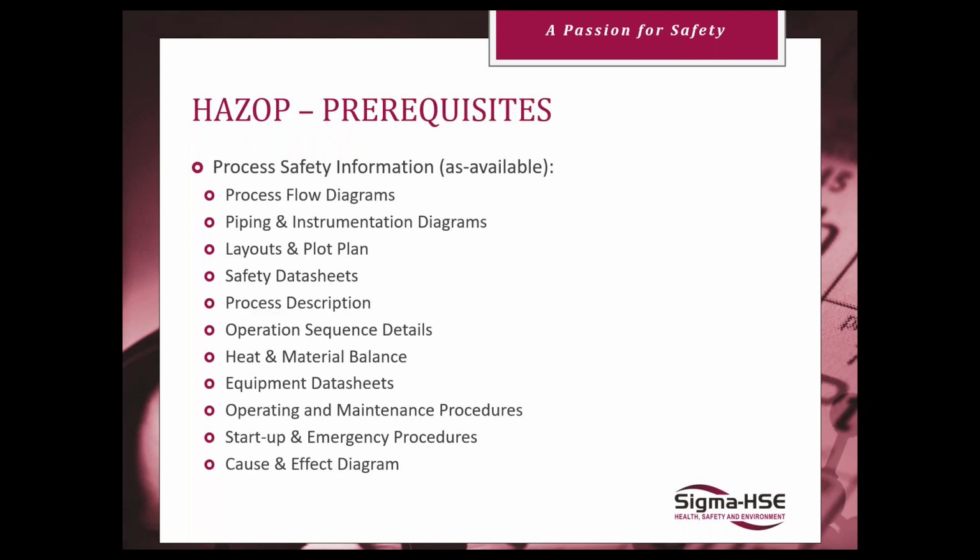Sometimes you'll have scenarios where it's a high risk, high likelihood, and HAZOP flags it, but you want to have a more granular approach. That's where company or corporate procedure may dictate, all right, this scenario is singled out for a LOPA, and you would then perform a layer of protection analysis in addition to your HAZOP for those scenarios.